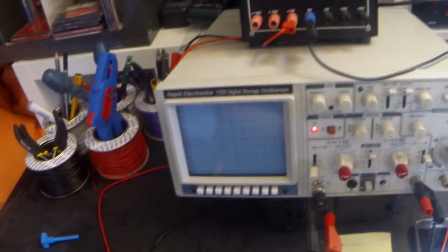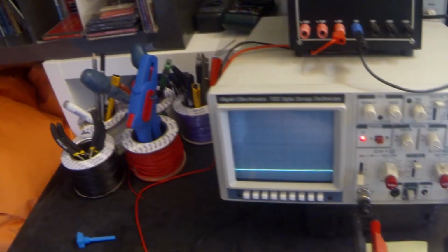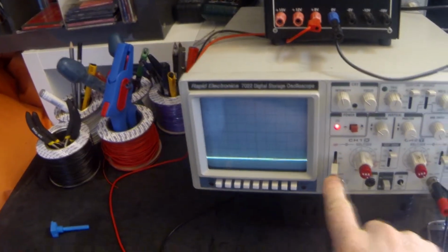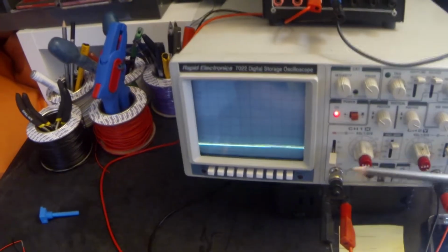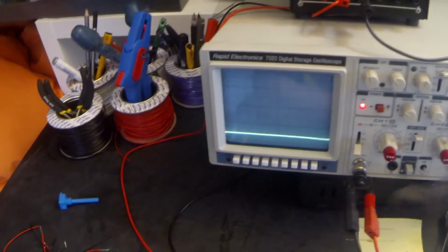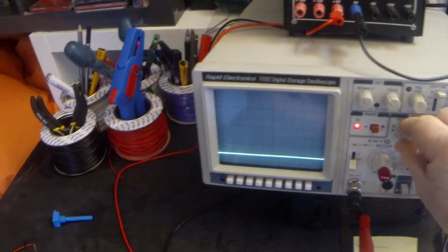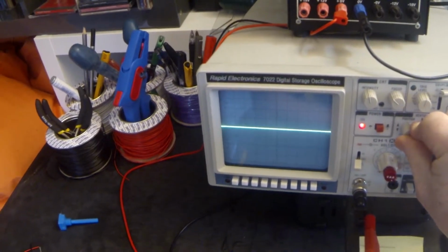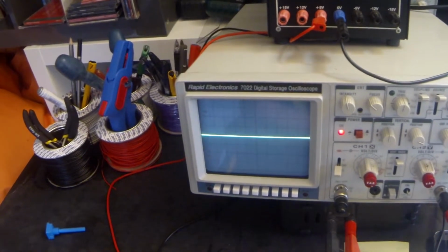Now, the oscilloscope requires quite a lot of setting up, so I'm going to turn my oscilloscope on and you will see a line appear somewhere on the screen. The first thing that we do, and we're going to be using just channel 1 in this. Your teacher can always help you set these up. I'm going to put it onto ground. And what I need to do is position that line on my channel exactly in the middle. That will make our measurements a lot easier.